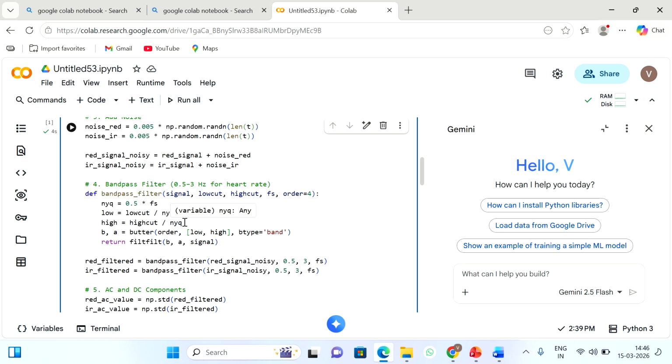And then, after filtering, it will finally return the signal with the numerator coefficient B and the denominator filter coefficient A. So why do we apply the filtfilt function? It applies the filter with zero phase distortion, giving a cleaner output.